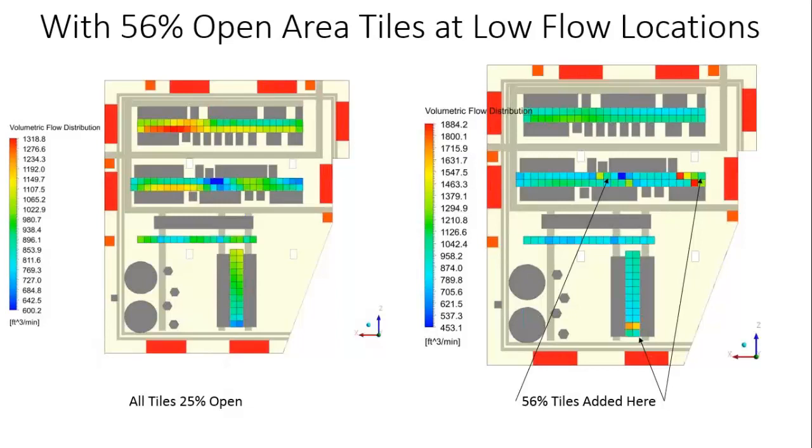It's kind of interesting. Yeah, and in my experience, and I can see Lance Miller made a comment about better where there are obstructions, and that's been my experience too. And then when you change tiles, trying to change airflow up into the rack, depending on what heat load each rack or a group of racks has, and the different open area of the tiles, I mean, it's all trial and error.